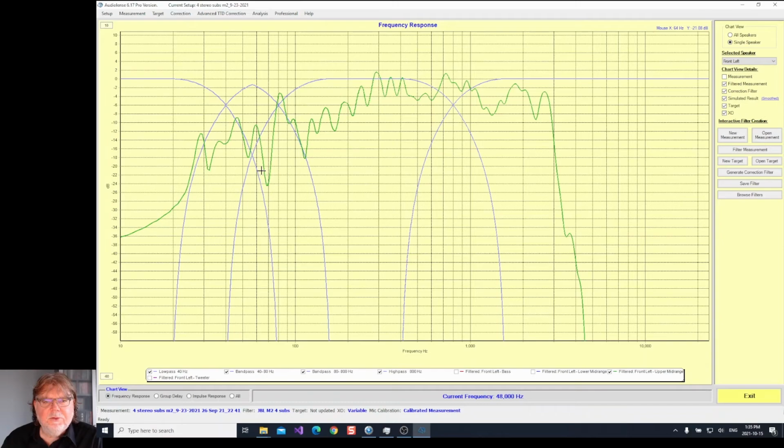We're bypassing those completely, and we're using AudioLens to provide not only that filtering, but as we will see just shortly, also some constant directivity waveguide EQ, which we'll need. But you'll see that the M2 woofer will fit nicely into the band pass from 80 hertz to 800 hertz, and so it's within its operational range, so when we convolve it into the crossover, it'll be perfect.